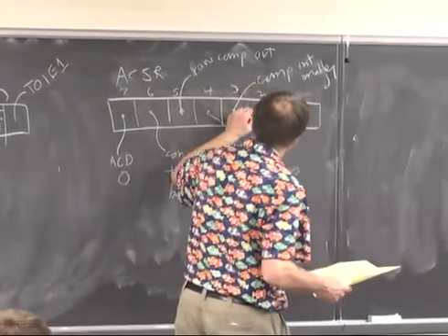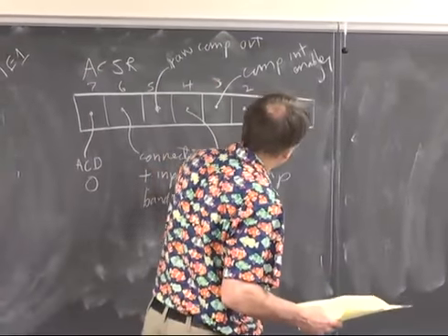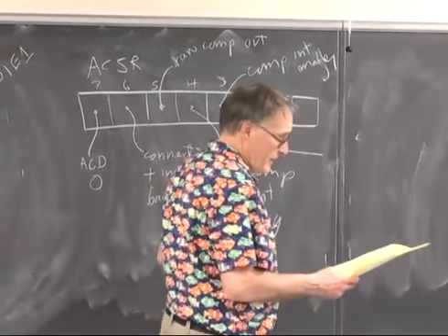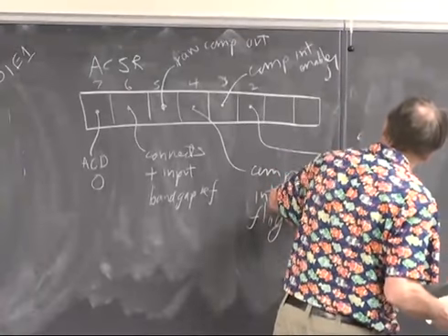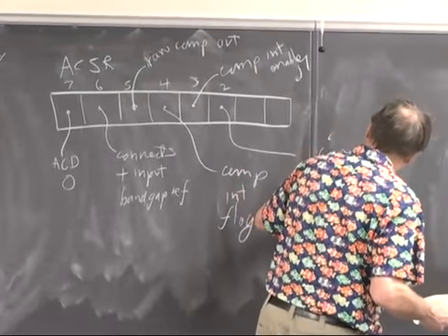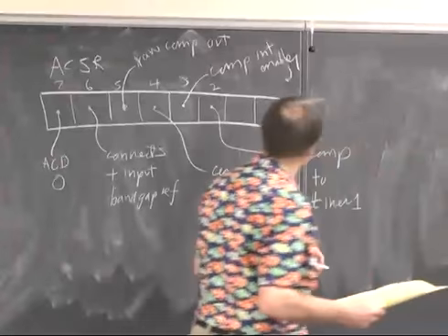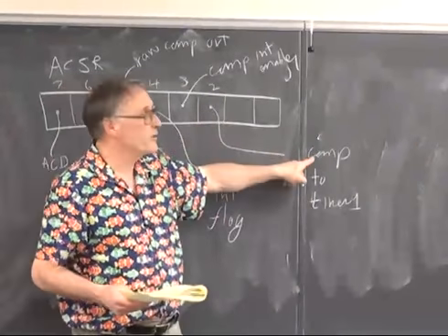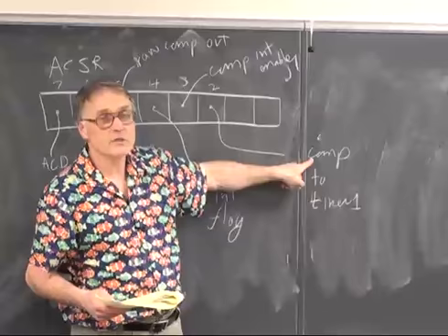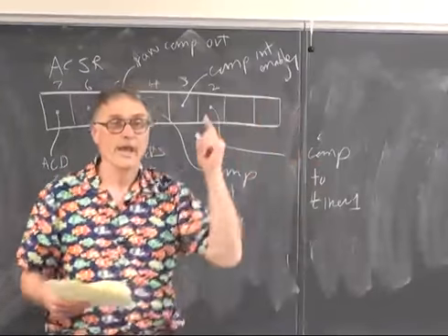Bit 2 is what you've all been waiting for, I'm sure. It connects the comparator to timer 1. When this is on, the comparator becomes the trigger source for the timer 1 capture.